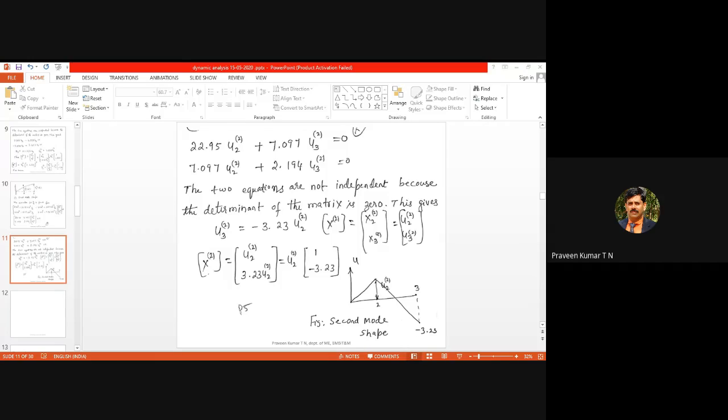A simple example is that you can pull a cantilever beam. After leaving it, it will start vibrating and finally come to 0. That is nothing but a free vibration. Forced vibration is when the vehicle is running continuously, and the vehicle is triggered or excited continuously by the engine. In the case of forced vibration, we have mx double dot plus kx is equal to f of t, where f of t is not equal to 0.